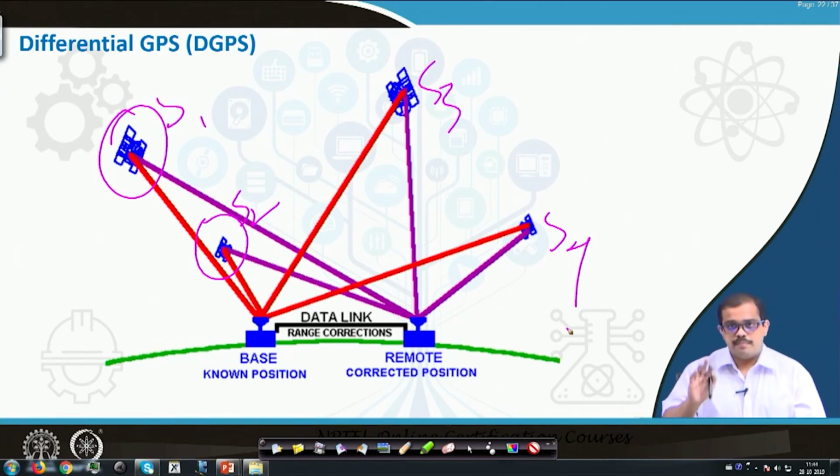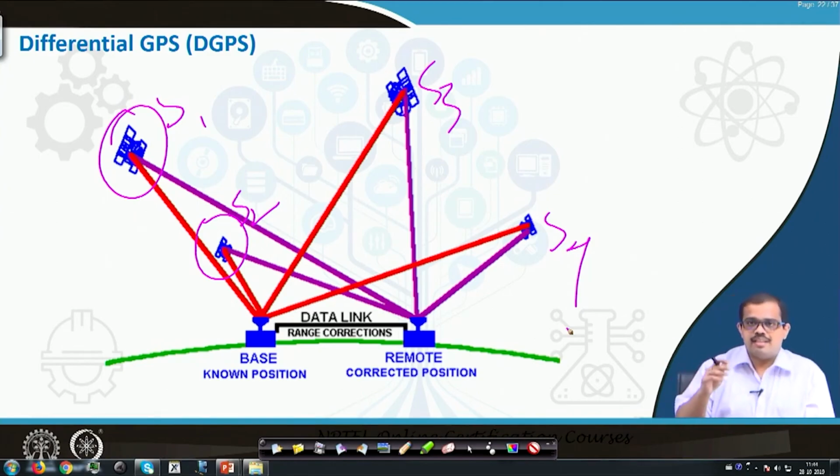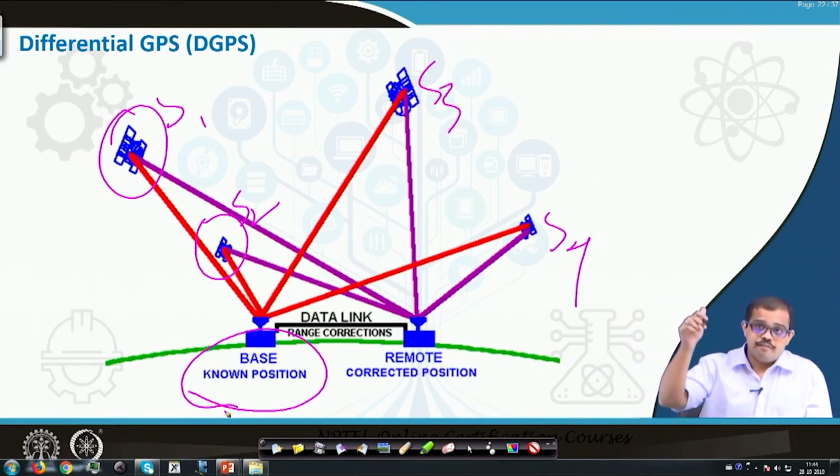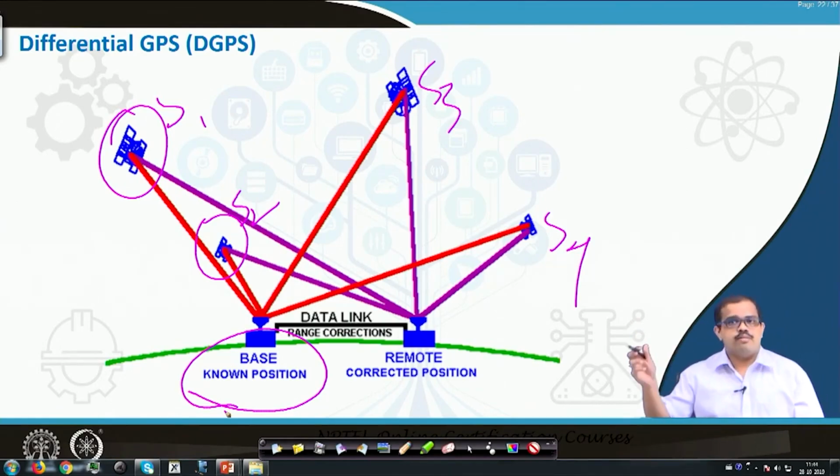Depending on the positioning system, we would fix a base station. Let us say we are trying to map the entire city; maybe our rover may not get the signal from the satellite's base station for the entire city. So we will have to shift the base station, then fix the base station, correct the errors around the base station, then make the rover move around that particular location.